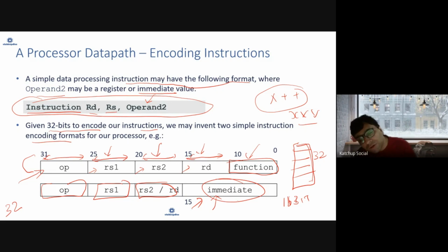So this is when you're using an immediate, but the data you can store immediately in our instruction set is just 16-bit. That limits some things, and you also have to take care that it's converted to 32 bits when you're doing the operations.